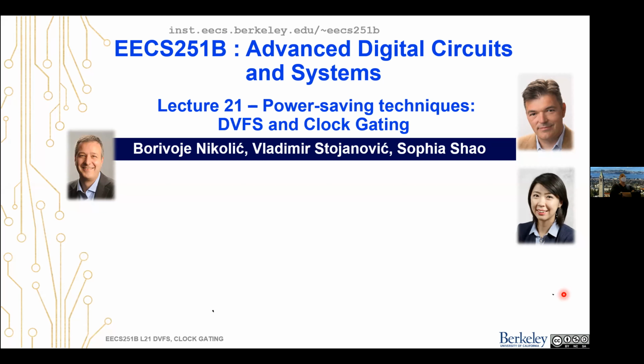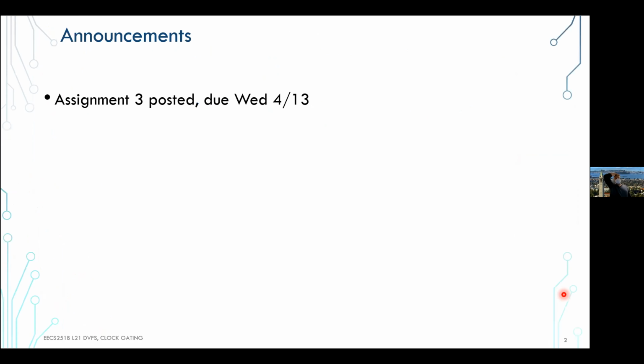Because you could do energy, power, performance optimization many different ways, and we'll keep flashing this table. But one of these ways is dynamic control of the system. So we're going to talk about some of these techniques, specifically dynamic voltage frequency scaling and clock gating in this lecture.